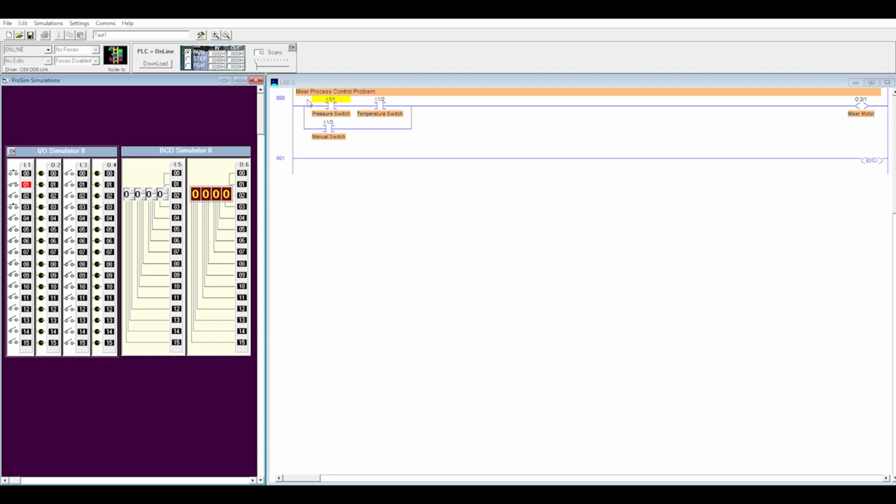If I go over and look at my program, we can see the address is now highlighted in yellow. This indicates that the statement is true. Examine if closed. Is the switch closed? Yes, it is. That's true. So that's why this is now true, working as per expectation.